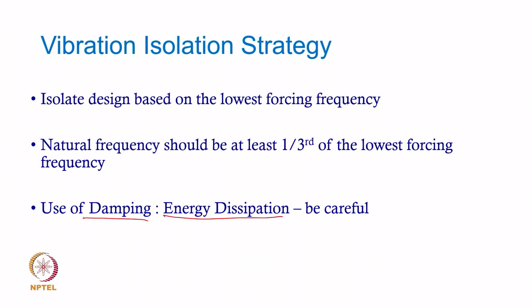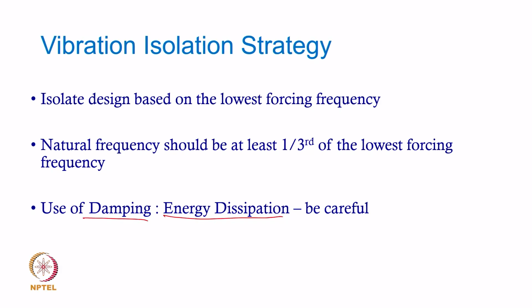Of course, there are other situations where you need to have a good amount of passive damping to take care of instability issues, but those are generally not encountered in normal vibratory systems, except when you have very high speed machinery, then the issue of instability can arise, and then some amount of additional damping could be useful. But as long as you are clear about what your system is and how much damping it needs, you do not have to use excessive damping in the system.